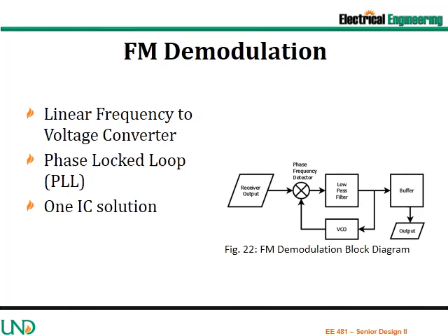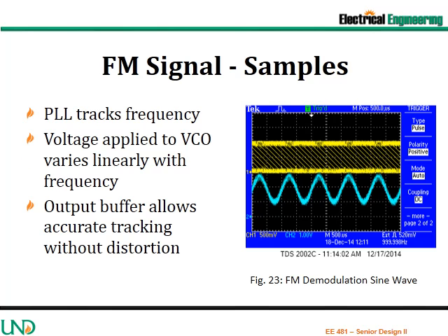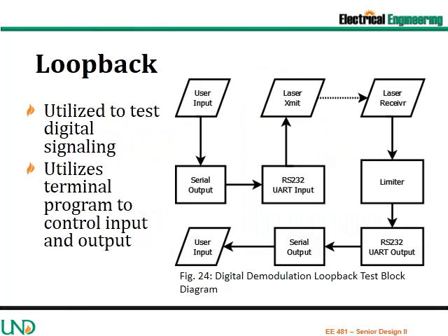Due to the high gain of the phase frequency detector, the phase lock loop will lock on to the receiver's frequency. The output from the low-pass filter is buffered for use to minimize loading of the phase frequency detector. The range of the frequency lock and offset determines the frequency to voltage transfer function. A smaller lock range equates to larger voltage changes for smaller frequency deviations. This comes with a price, as jitter of the source oscillators as well as the receiver oscillator directly equates to noise. A loopback function is utilized to test the transmission of digital signals.